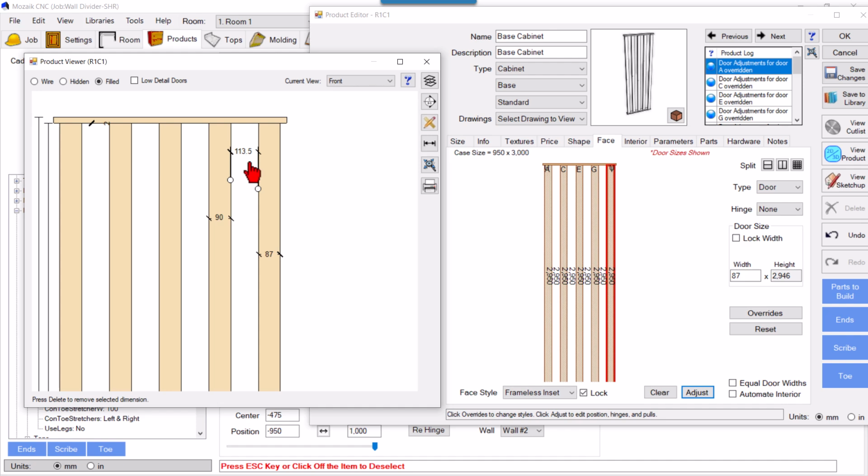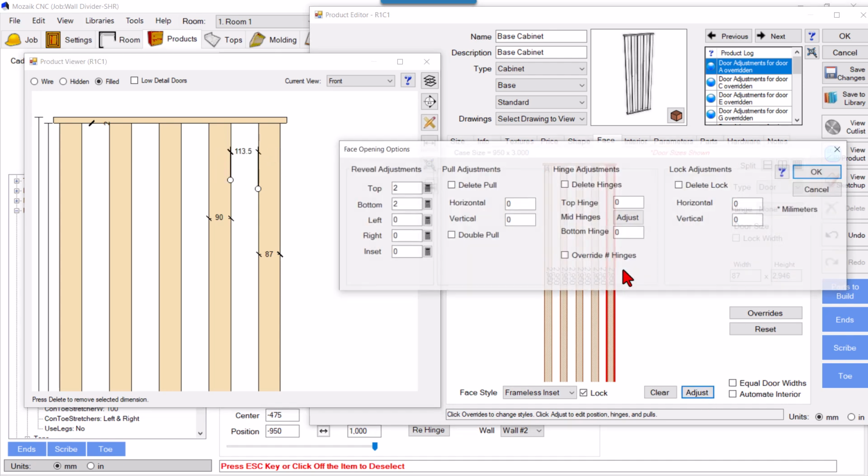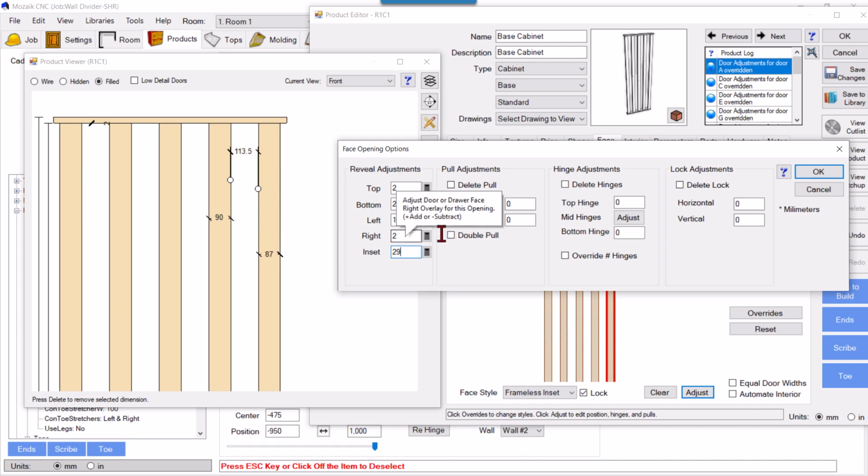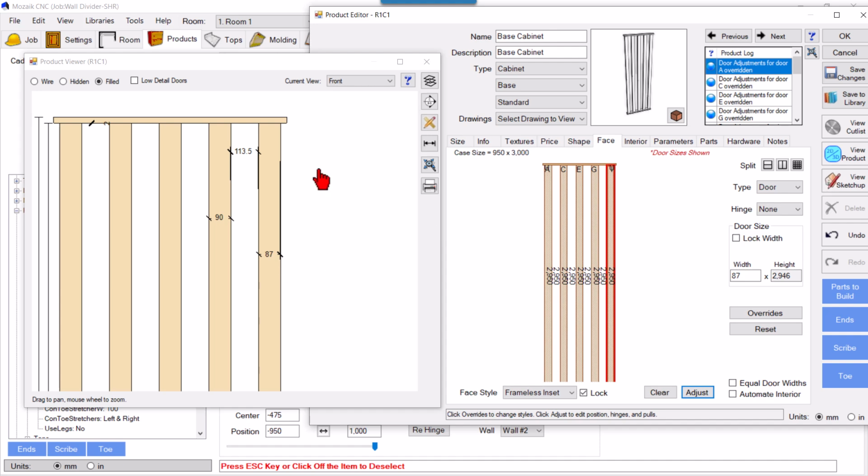reduced by, increased by 1 millimeter, and right side should be increased by 2. If we increase left side of this panel by 1 millimeter towards left, then this gap will become 112.5. At present it is 113.5, right? So we will adjust this. Left should be by 1 and right should be by 2 instead of 29, right? Because in case of these ends, which are closer to our end panels, unfinished end panels, this left and right gap is a little bit different.